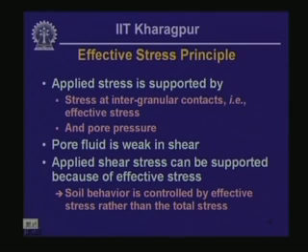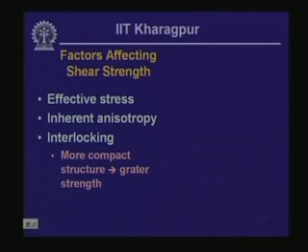So soil behavior in shear stress shear strain response is controlled by effective stress rather than the total stress, and this is the effective stress principle introduced by Karl Terzaghi in the early 1900s, which led to the development of the science of soil mechanics and geotechnical engineering. It's a very important principle, actually seminal in fact, that led to the entire development of this field of learning.